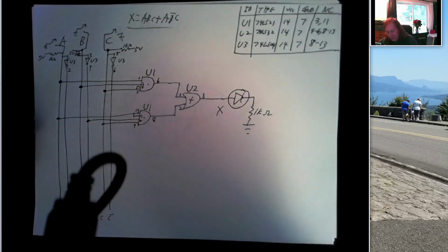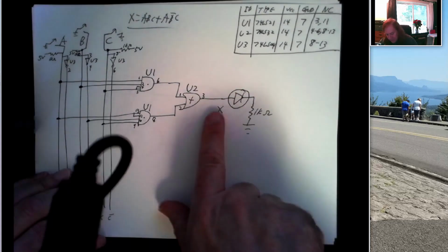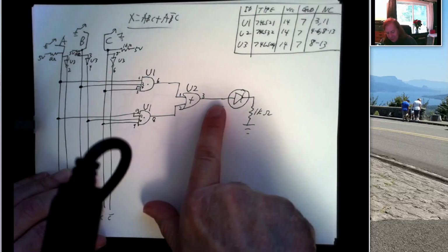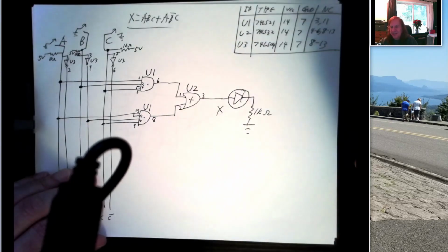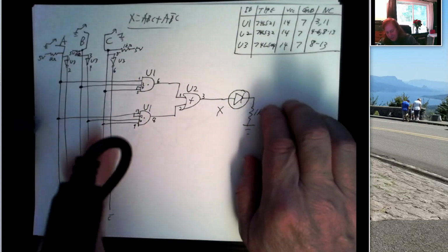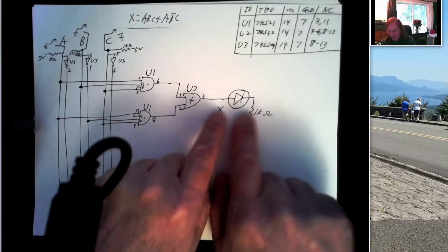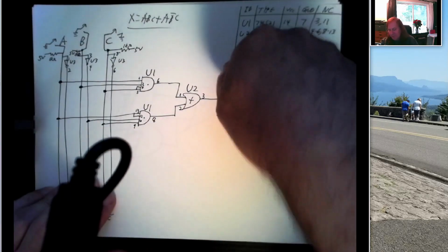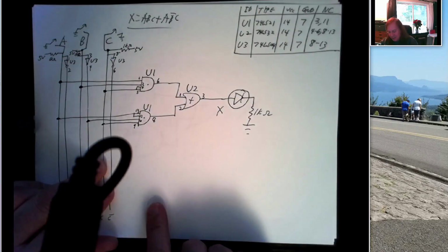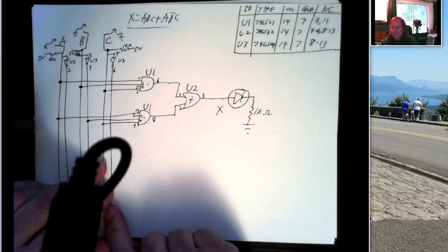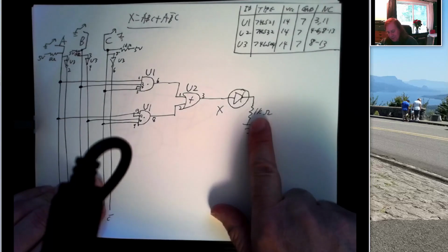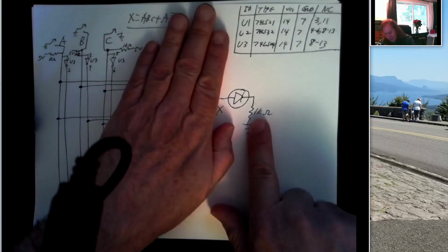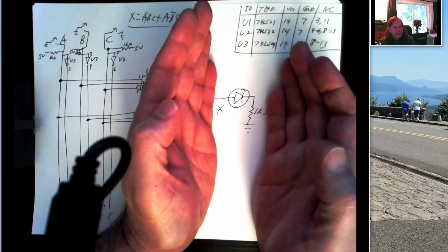Well, you can get a multimeter and you can take a voltage reading right here and say, what's the voltage here? If this is 5 volts, something's wrong with your LED. All of this circuitry is correct because this is generating the correct 5 volts, but your LED is not lighting. Maybe it's backwards, maybe it's a bad LED, maybe it's not connected to ground through a resistor. Maybe this is a 1 mega ohm resistor instead of 1 kilo ohm. But you've isolated your problem to somewhere right here.